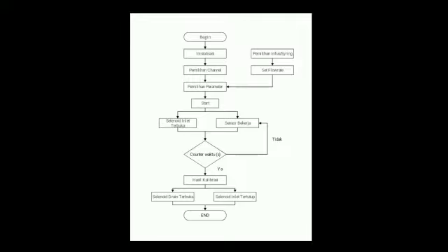Furthermore, the tool will do the second and third measurements with the same process and setting but with a different sensor. When the final measurement results appear, the inlet solenoid is closed and the drainage solenoid automatically opens for water discharge.